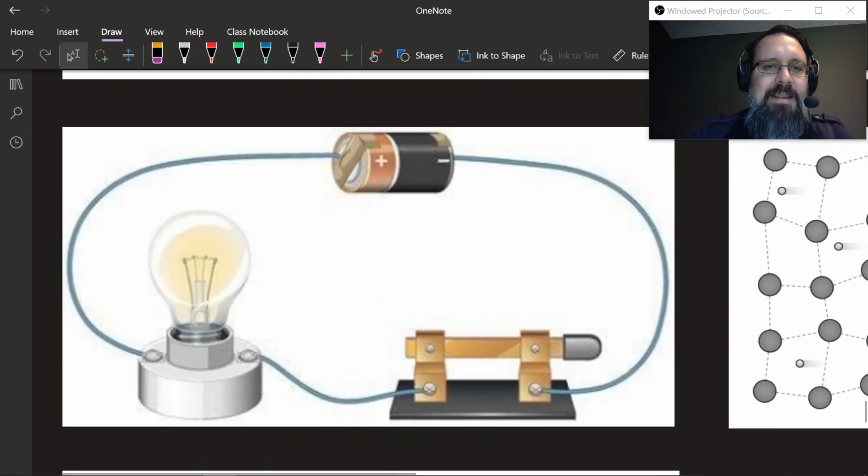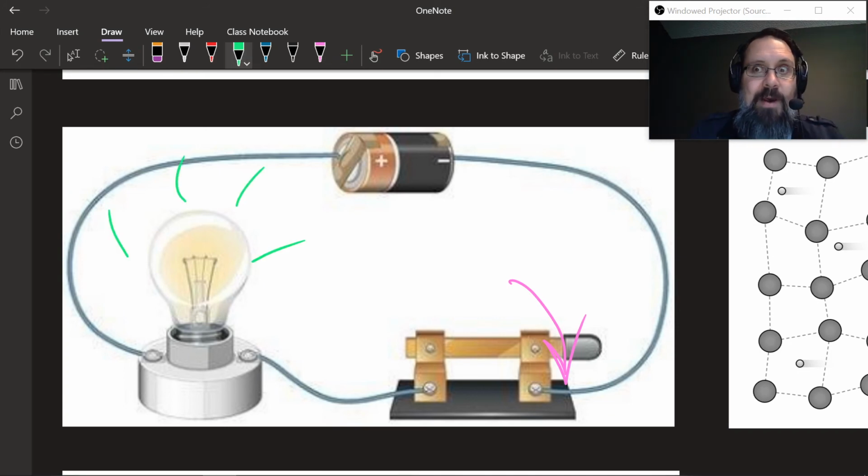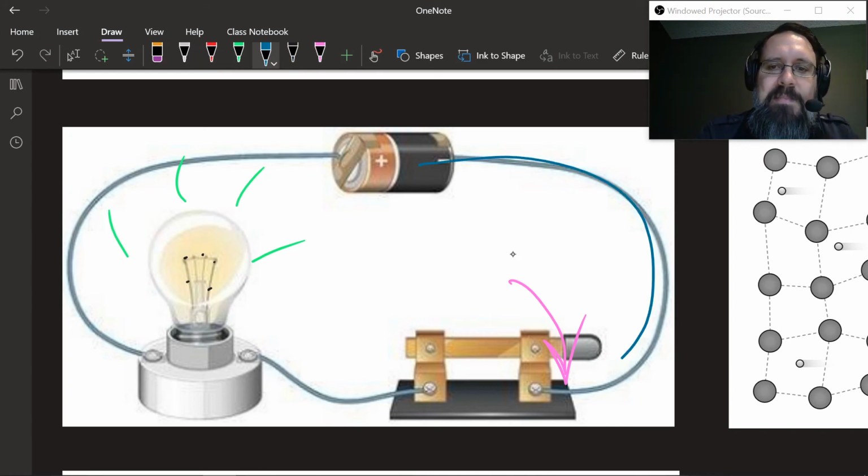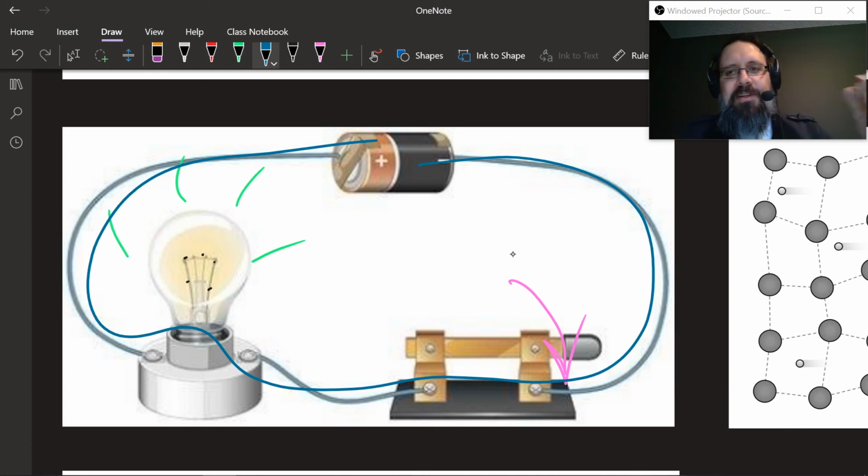And so the thing is that when I flip this switch, so boop, I'm going to flip down this switch, the light bulb turns on instantly. So we get light right away. And the reason is because there's a wire here and there's free electrons inside that wire. And so as soon as I flip the switch, the electric field gets immediately established all throughout the wire. That gets established at the speed of light. It jumps through the circuit really quickly. And then every single charge that's inside these conductors, every single one of those charges immediately starts to flow.